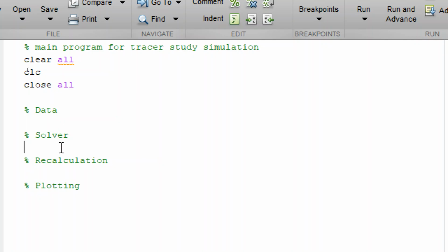And now we will use the ODE solver. In this case, the best ODE solver that we have in MATLAB is ode15s. So we can have the output first. This is t and then C. So we'll have a large matrix of C later on. And then you can write ode15s. The first place is for the name of the subroutine. Make sure that you put everything in the same folder. The name is myfun9D.